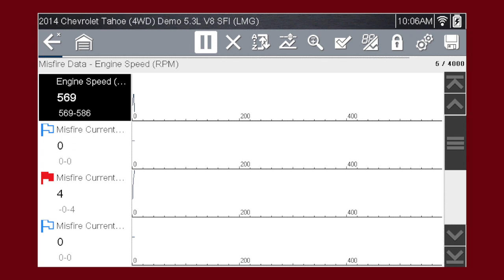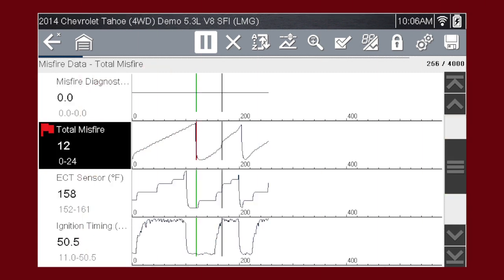With the PID now triggered, Smart Data uses colored lines to help show when the PID crossed the min-max value. In Graph View, take a look at one of the triggered PIDs. We can see that after a PID trigger has been activated, a red cursor line is displayed on the graph of the PID with the activated trigger to indicate where the trigger occurred.